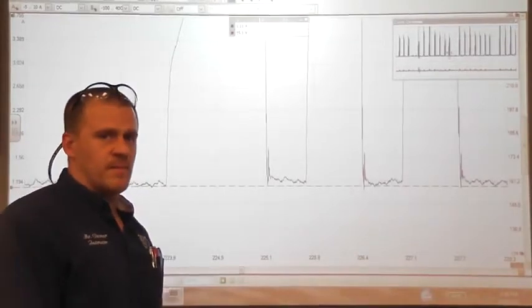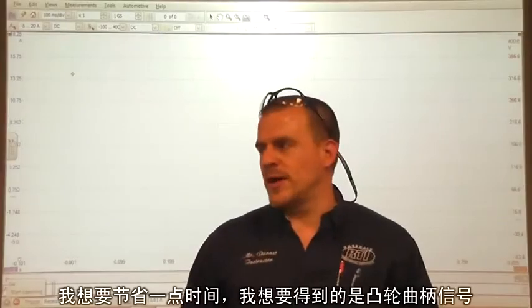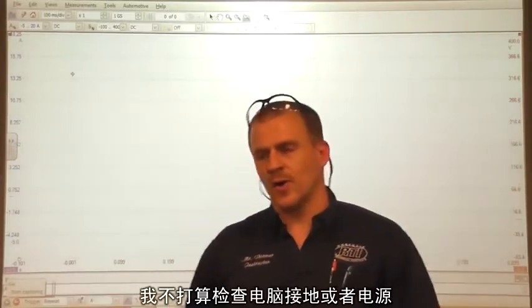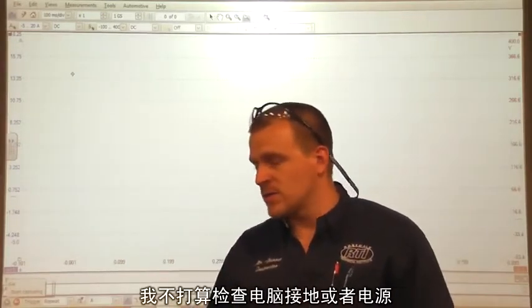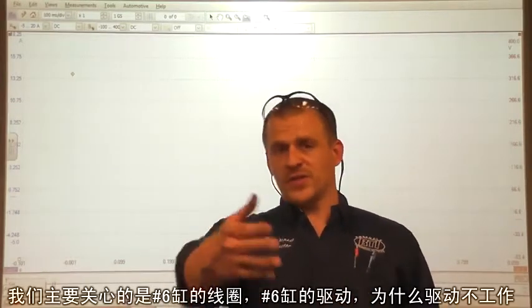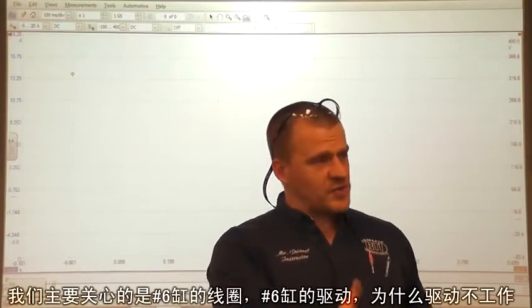Cylinder 6 current ramp. Okay, what I'm going to do to try to save a little bit of time here, we're not going to do cam and crank signals. We're not going to check computer powers and grounds. Our main concern is this number 6 coil, our number 6 driver. Why is this driver not functioning?